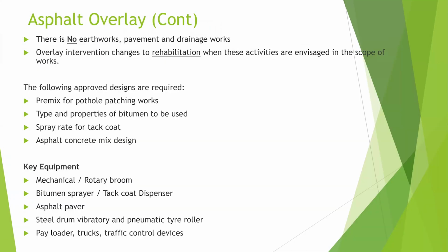Here there is no earthworks, no pavement, and no drainage works. For asphalt overlay, you are not supposed to undertake earthworks, pavement works, and drainage works. Now, overlay intervention changes to rehabilitation when the above, that is the earthworks and the pavement works and the drainage works, are considered part of the scope. Immediately these activities become part of the scope of works, then it changes the definition of the overlay to a rehabilitation.